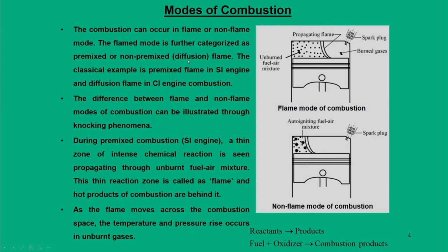Non-premixed flames are known as diffusion flames. So mainly in SI engines, the combustion is initiated through a premixed flame, and typically both mixed as well as non-mixed diffusion flames are part of CI engines. We will discuss about that. And if you broadly look at the flame and non-flame mode combustions, they are detected by knocking phenomena.